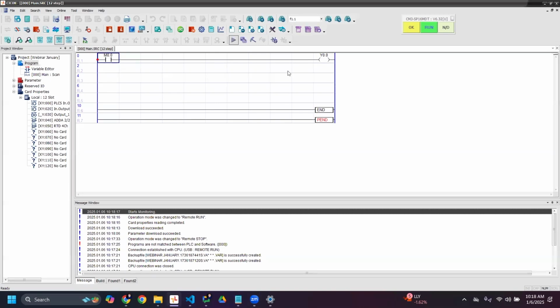And to interact with contacts or coils, we actually can do that as shown here. So I'm going to left click on the open contact, and I'm going to press Shift and Enter. So holding Shift and pressing Enter will allow me to energize the coil and the contact, shown by that blue button. So it is on, therefore my coil is on.